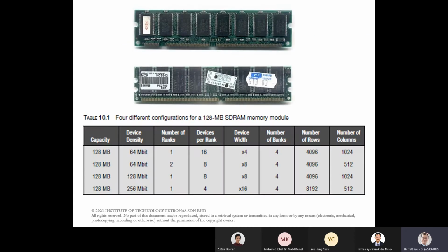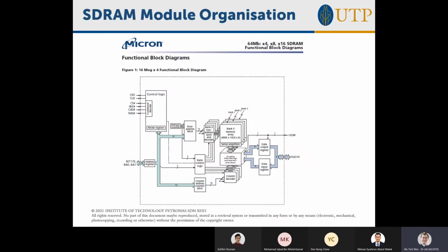Okay, so now I'm going to talk a little bit more about DRAM organization. How are we organizing these chips in a system so that you can see the full breadth of the complexity, why we need to figure out all this, because the storage doesn't just end there. It gets more complicated because within the DRAM chip, you have something called banks, and you also have something called ranks. Banks and ranks. This is just how DRAM is organized, because you will never find a 64 gigabyte DRAM chip. You will never even find a 1 gigabyte DRAM chip. I guarantee you that. If you do, technology has moved a step up.